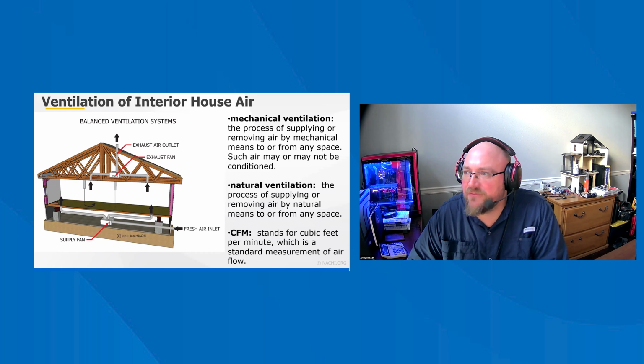Historically, homes did not have requirements for ventilation because air leaks through the building envelope and natural ventilation were considered adequate. As envelope construction techniques and materials have improved, the need to control indoor air quality in the home has increased. Today, many residential building codes require a home to have adequate mechanical ventilation systems installed with controls for the occupants to use. Each mechanical ventilation system, supply, exhaust, or both, should have a readily accessible switch or other means for shutoff or volume reduction and shutoff.